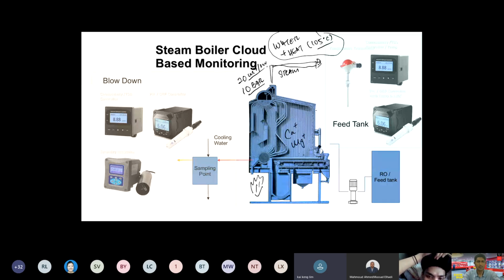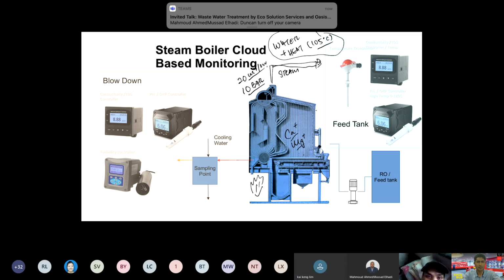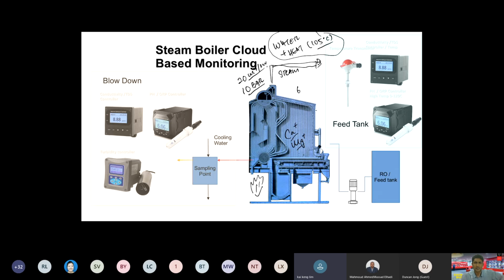Okay, students, calcium and magnesium are good for building bone in our body, but they are not good for a boiler, because the minerals left behind cause scaling. Scaling will drop heat efficiency. If I'm not mistaken, 6 mm of calcium scale, or what we call a deposit, will reduce heat transfer by 30%. This is where we waste a lot of burning fuel because of improper water management. That's why, at the second slide, we talked about wanting good quality water. That's one of the reasons why we need this.